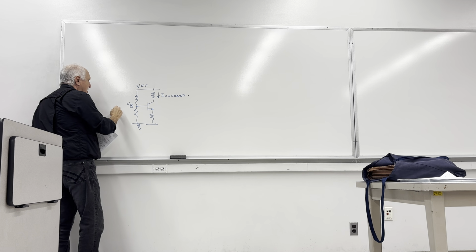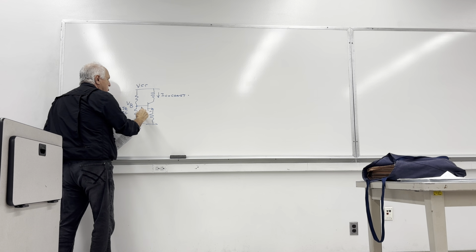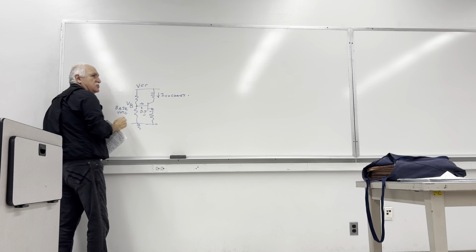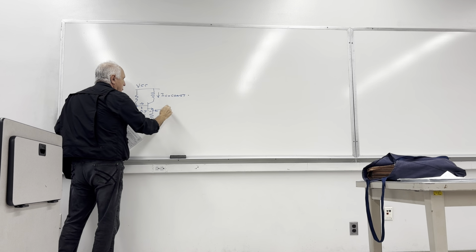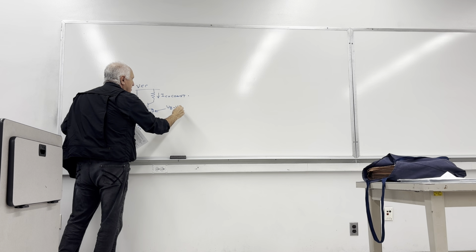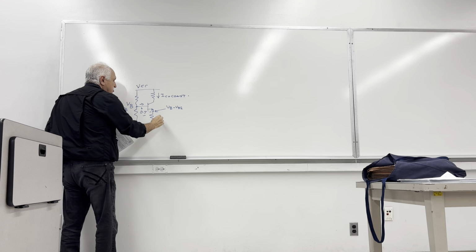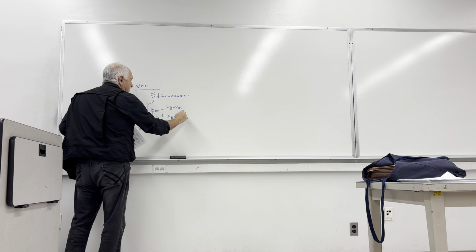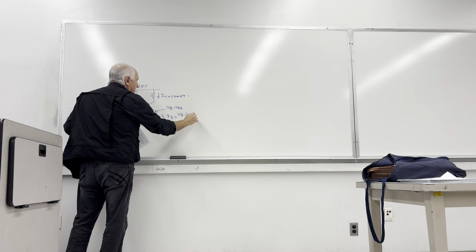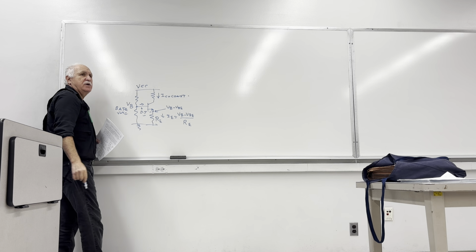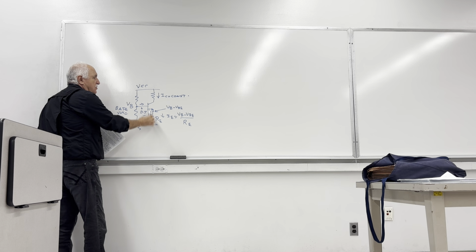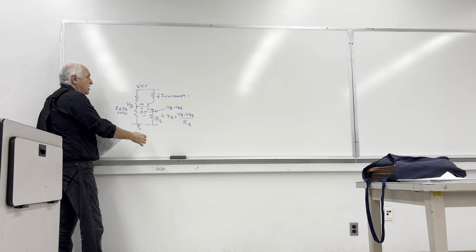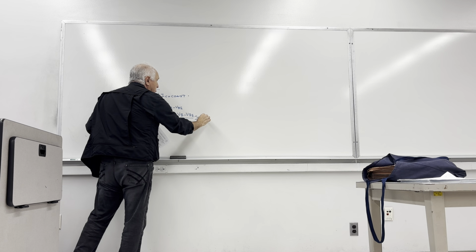This is base voltage. Then we know that the transistor drops 0.7 volt whenever current flows. So this voltage will be equal to VB minus VBE. And if you put a resistance in here, RE, then IE will be equal to (VB minus VBE) over RE. And IE will be a constant current generated in the emitter path, which will approximately equal IC.